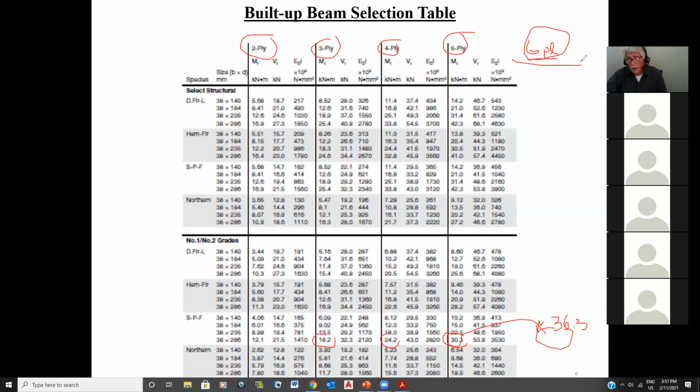Because of the bending moment, because of the resistance, all these values are based on the B value here. So in other words, 1-ply, 2-ply, another B, another B. Everything is based only on one variable, and as these increase by adding another ply, all the values are linear. There's nothing squared, nothing quadratic, nothing cubic. So you can just extrapolate linearly if ever you want to get to a 6-ply.